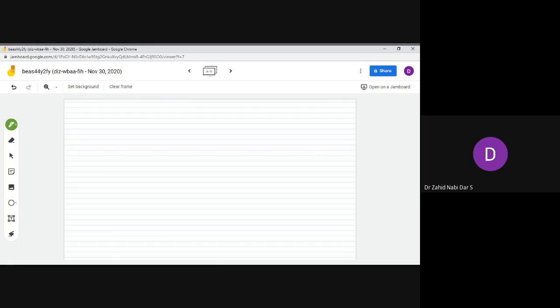Let's take one example to understand the supernode in a better format. So basically, what does the nodal analysis technique cover? First we have to label the nodes, then take a reference node, then apply KCL. Once we have applied KCL, we express it in terms of resistance and voltage via Ohm's law. These are the steps involved in nodal analysis. Now let's go for the supernode technique and understand it in a better way.